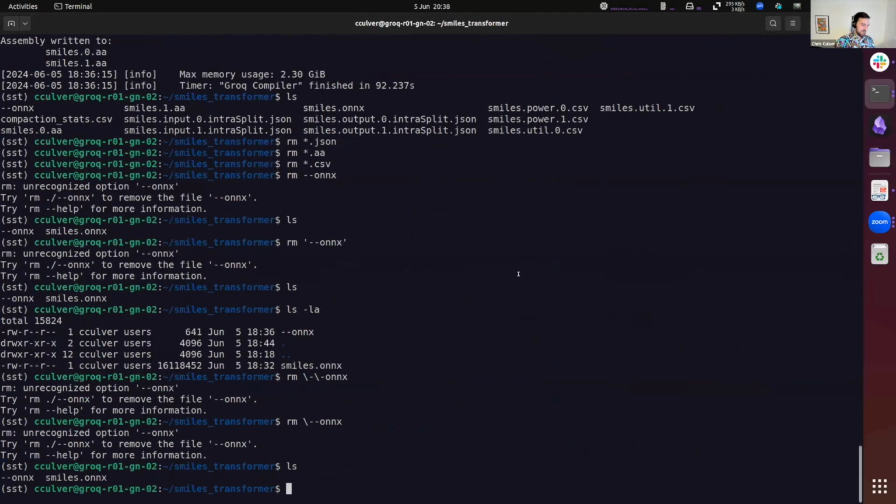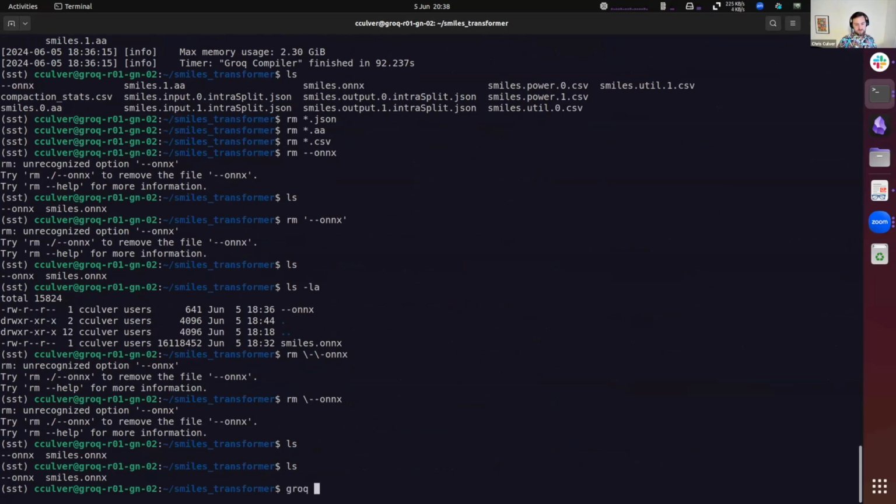I already transferred it onto the ANL rack. So I'll go ahead and run the compiler. For the sake of showing you a little bit of extra, I'm just going to compile it for 2 chips. The way to do that is to include a flag titled --multi-chip. And then there are a bunch of specific flag options, which I've listed in the slides.